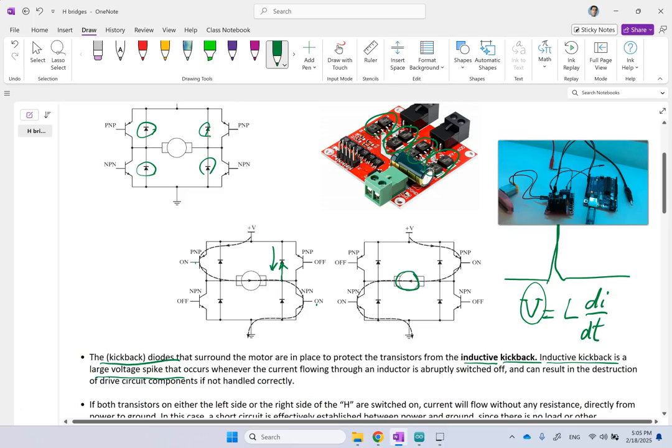Okay, so if you can see here, when this voltage is created, if it wants to basically go back, right, this is the direction of the flow. But when this voltage is created and it wants to go in the opposite direction of the current and damage the windings, this diode says, hey, I'm not going to let you flow through me, okay? And it is going to kill that inductive, what we call kickback. So these are protective elements from the back currents from the inductive kickback flow.